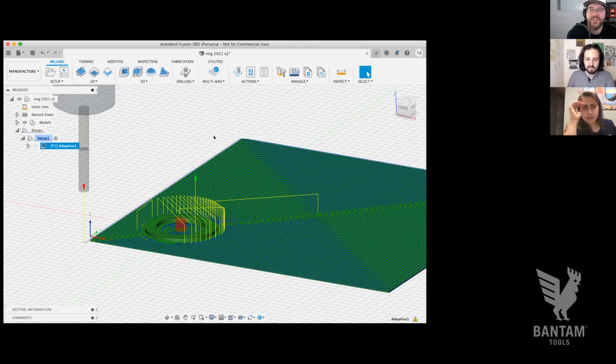And then you also have to worry about the life of your tool. You're going to want to think, hey, I don't want to be that aggressive, because while the mill is powerful, it might not be that powerful. The CNC mill would have no trouble doing this cut, but the PCB mill would probably have a little trouble. It's not optimized for removing that much aluminum that quickly.